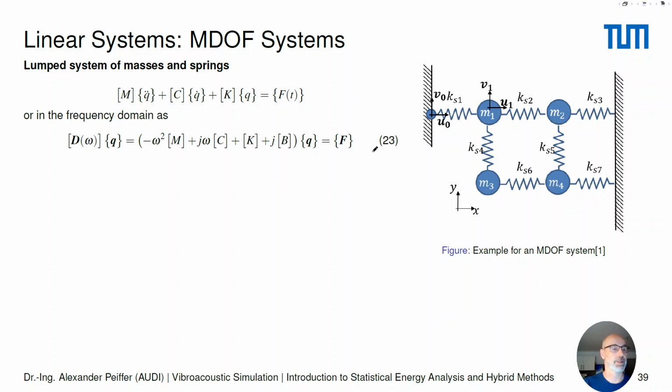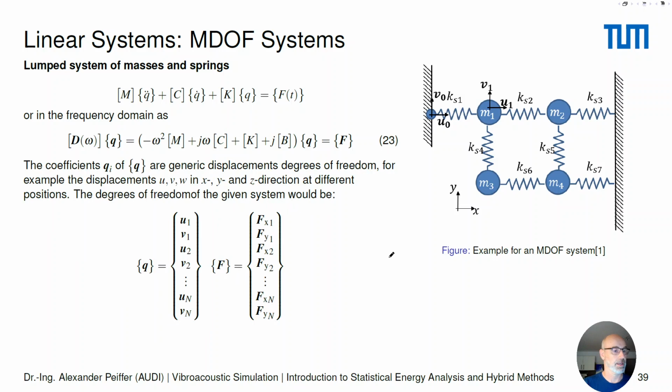Again, we use the complex notation and write this in the frequency domain, and then we get our omega terms with different factors, and we also get the C factor. Just to mention, there might be some damping directly related to the displacement, as we have seen in our damping chapter, and this would be used in such a way. But globally, in the next studies we will more or less neglect the damping parts and just stay with the remaining mass and stiffness matrix.